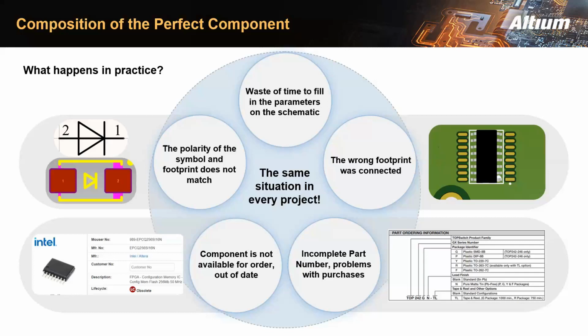From the point of view of the circuit designer, there is no difference in the symbol, but from the perspective of PCB designing and purchasing, the suffix defining the package type is critical. Fortunately, the procurement department will typically ask which one to buy, but sometimes they don't inquire.